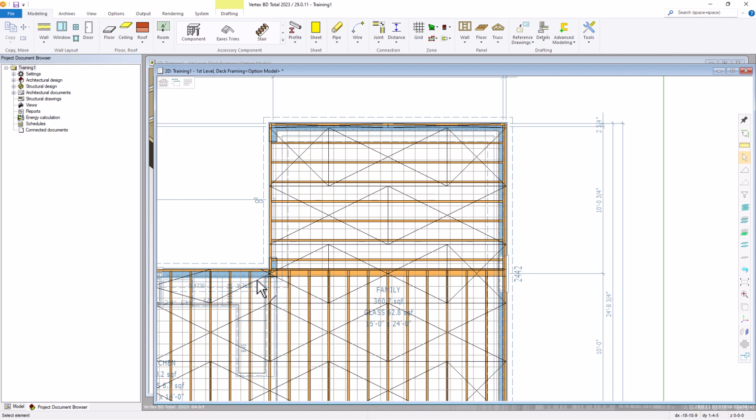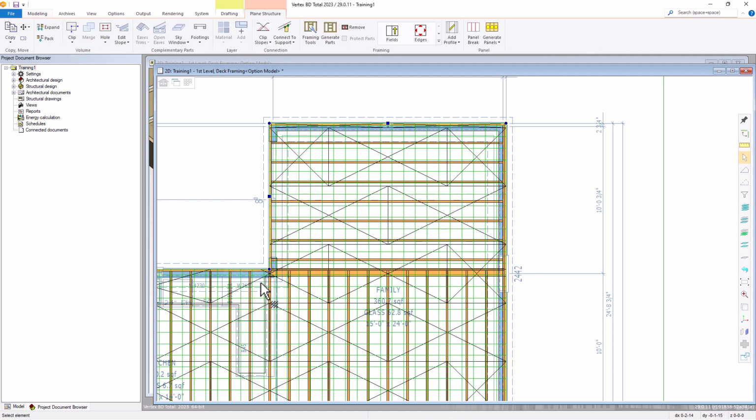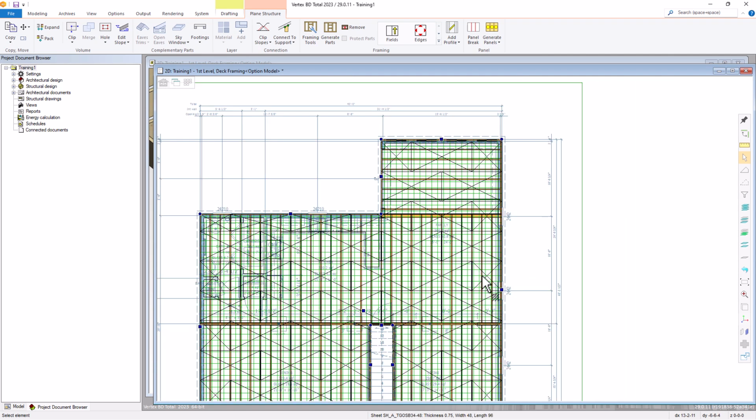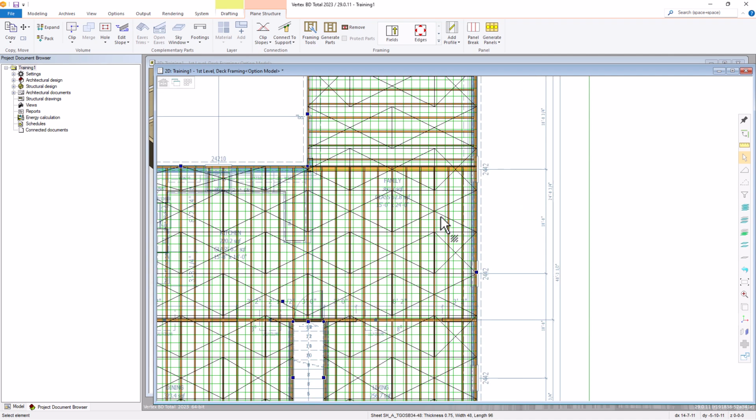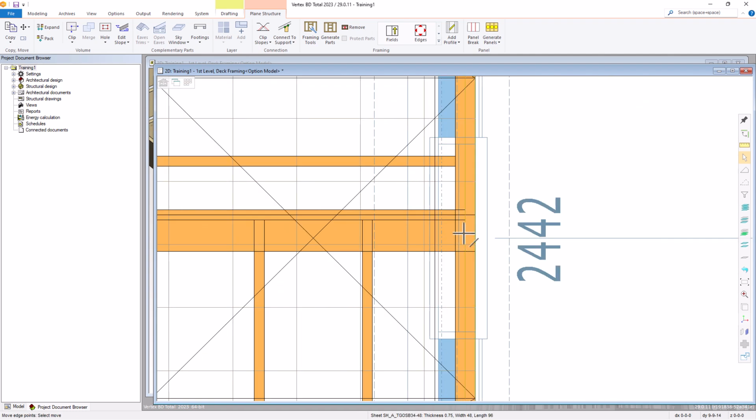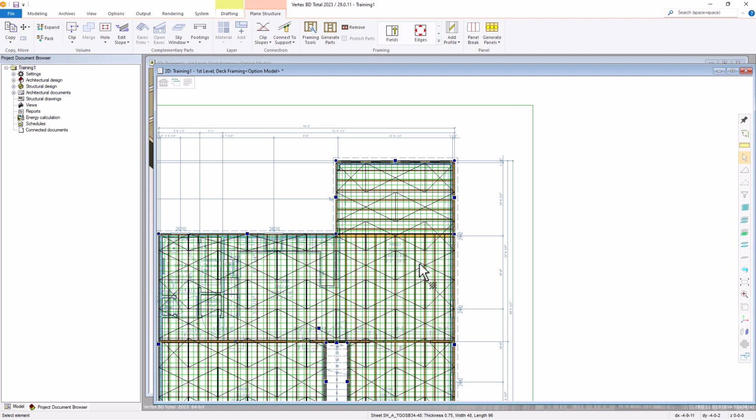So we select our floor area. We need to add an additional endpoint, just as similar to what's shown here, but we need to add one at this location. Zoom out. Find that middle grip point, right click, and we want to add a point along this edge. We'll bring it in line with the edge of our rim. Now let's go ahead and generate our part.